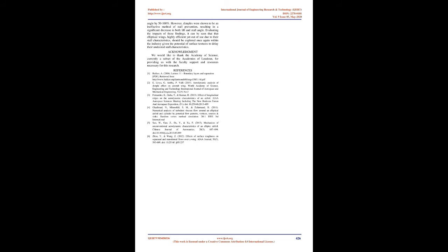The quantitative analysis from the lift graphs at the beginning of the section is further supported by a qualitative analysis of the velocity heat maps on a cross-sectional plane through each wing obtained during CFD post-processing. As seen in Figure 7 and Figure 9, both the reference and dimple wings had significant boundary layer separation at a 25 degree angle of attack. The velocity heat maps also show boundary layer separation points near the leading edge and behind the wing. These points show that both the reference and dimple wings are nearing stall or have stalled.